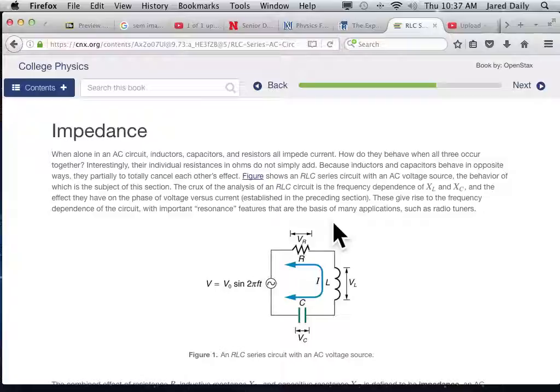So when the magnetic field is really high in the inductor, the electric field is really low in the capacitor, and back and forth and back and forth. Well, not necessarily all the time, that's not always the case. It depends on the frequency, and on the different values of the capacitor and the inductor. Sometimes if you have a really big inductor, it takes longer for that inductor to fill up its magnetic field, and it takes less time for the capacitor. So you can start changing things, and all these voltages can be really out of whack with each other.